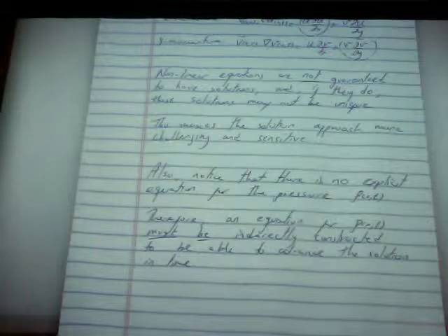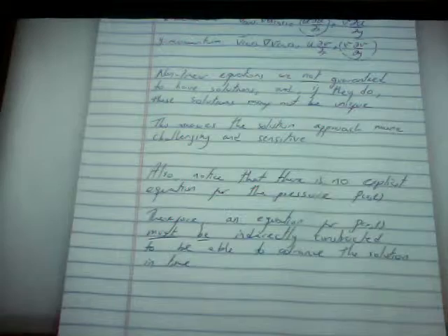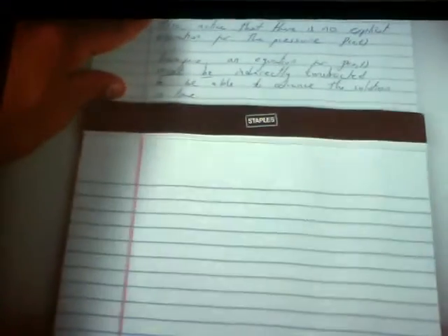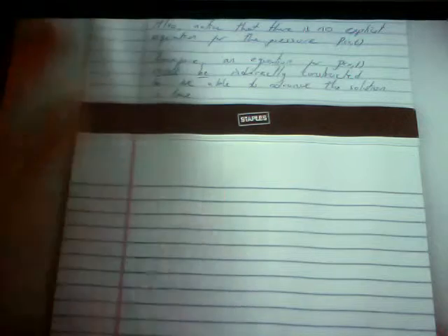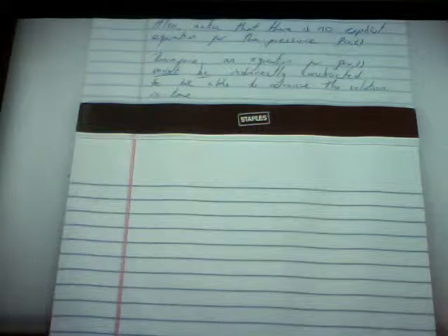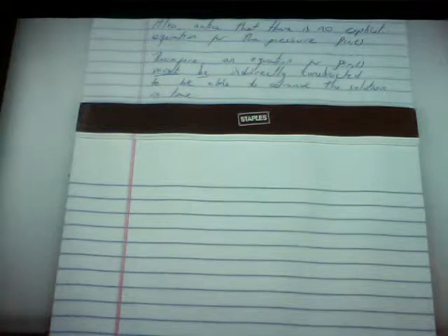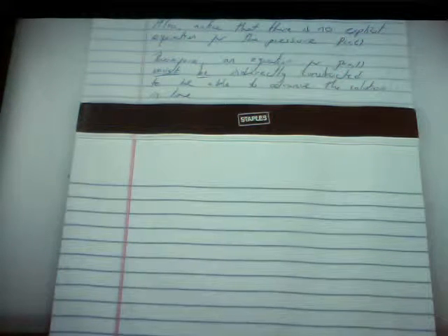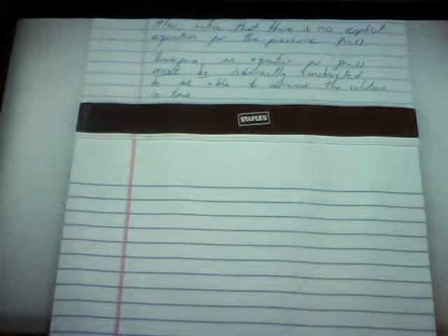All right. So now we know why these little equations here can be so complicated to solve, and there's actually no analytical solutions to these equations, only very simplistic forms of these equations. 1D, very slow flow, like Poiseuille flow, or Couette flow, like cylindrical flow, rotating cylinder, very slow speed, Stokes flow, when the flow is creeping. Very, very specific solutions to this equation, or versions of this equation with high simplifications, would lead to analytical solutions. In the general form, not even in a square.